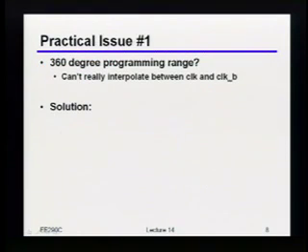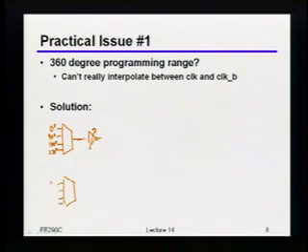So what you will typically do is something like the following. I'm going to draw it with 4 phases now, but by no means is it limited to 4 phases. It could be any number of others. So this would be 0 degrees, that would be 90, that would be 180, and that would be 270. I'll pick one of those phases and feed it to this variable weight inverter we just drew. I'll do the same thing on that second inverter: again 0 degrees, 90 degrees, 180 degrees, 270 degrees. I'll pick another clock, feed it into that second inverter, and then just tie their outputs together and buffer it out.